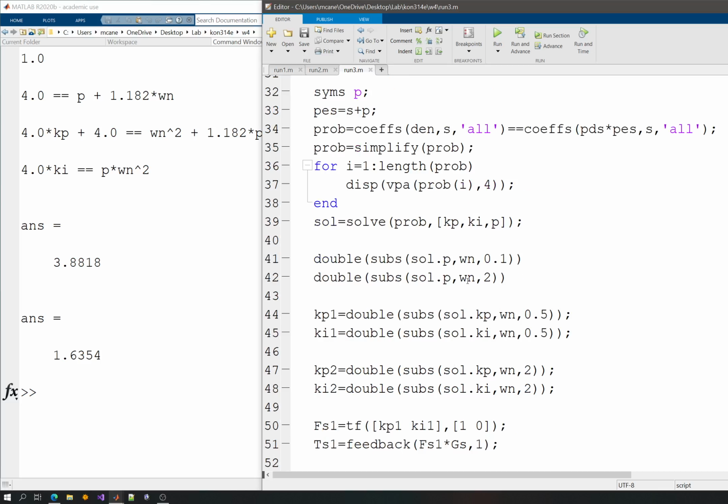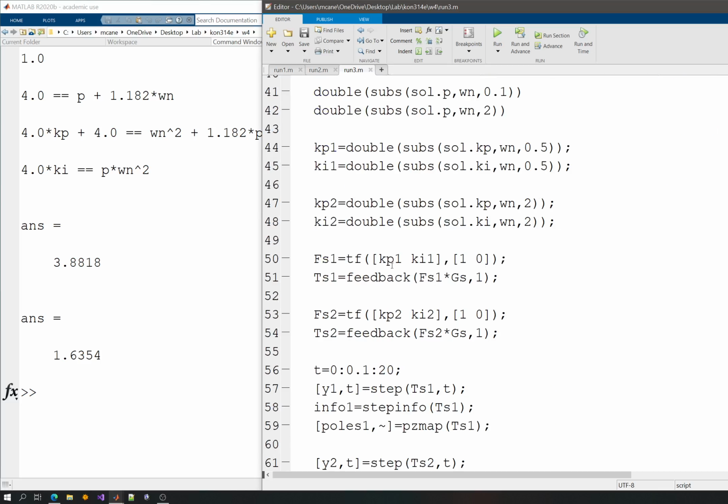Now I can easily determine where the position of the zero is. It's exactly related to this numerator here. Kp1s plus Ki1 gives me the position here. Now I can determine the position of my zero, and since this is Kps plus Ki, the solution is at minus Ki divided by Kp.